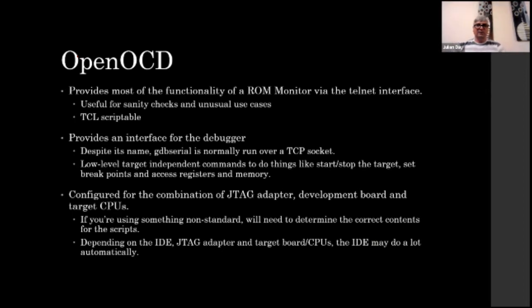So yeah, OpenOCD provides most of that ROM monitor capability, and it also has TCL scripting available. So if you're trying to do some complex board setups, which sometimes are necessary, that's all possible. In terms of the debugger interface, GDB serial is the interface that's used.